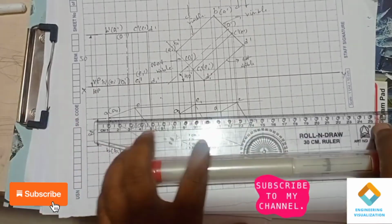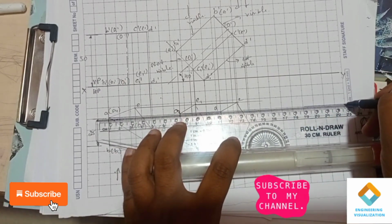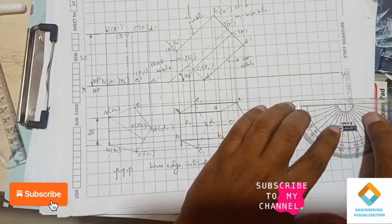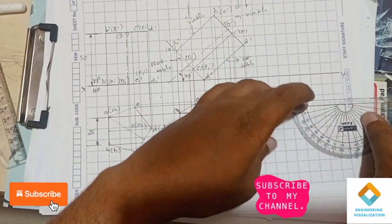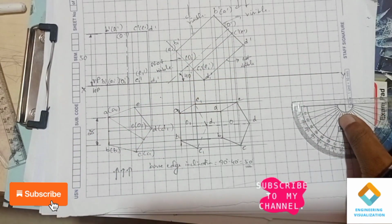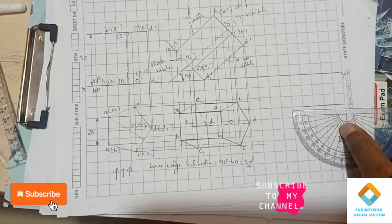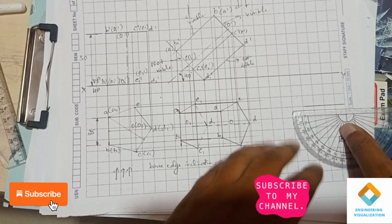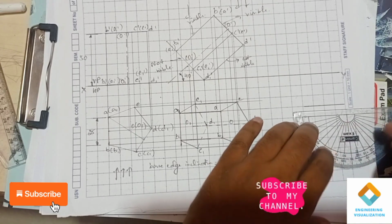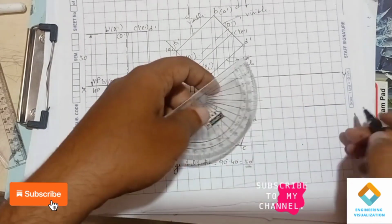You need to make sure about the space to be constructed here, so that the second diagram, when we copy it, should not merge with the XY line or leave the page. You should be careful when drawing an angle line. I think I should take the angle line a little lower so that the diagram can be copied easily. So from the reference point you can mark an angle of 30 degree.